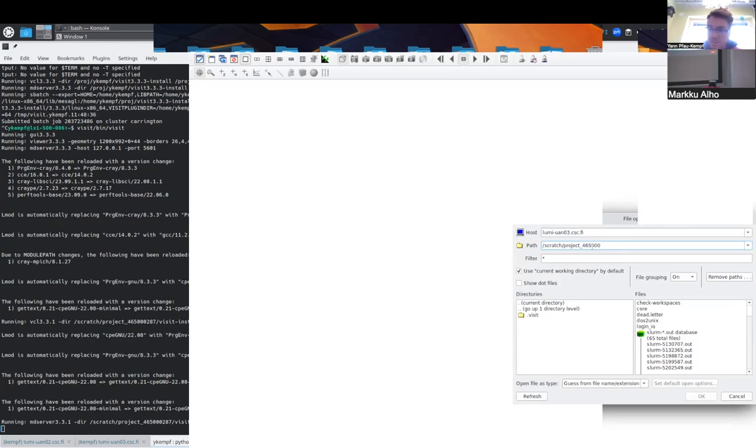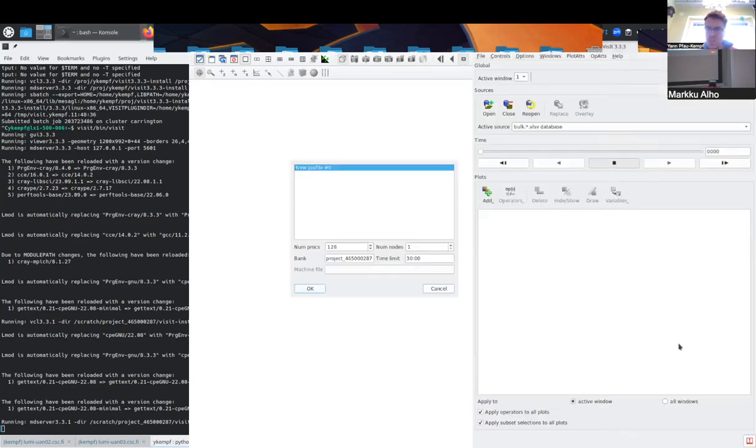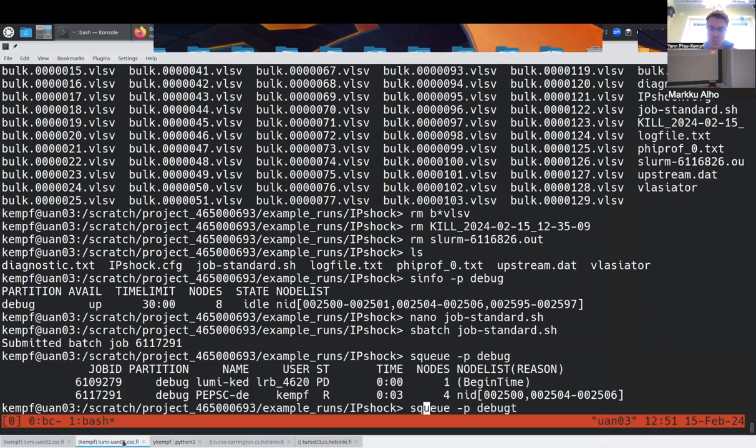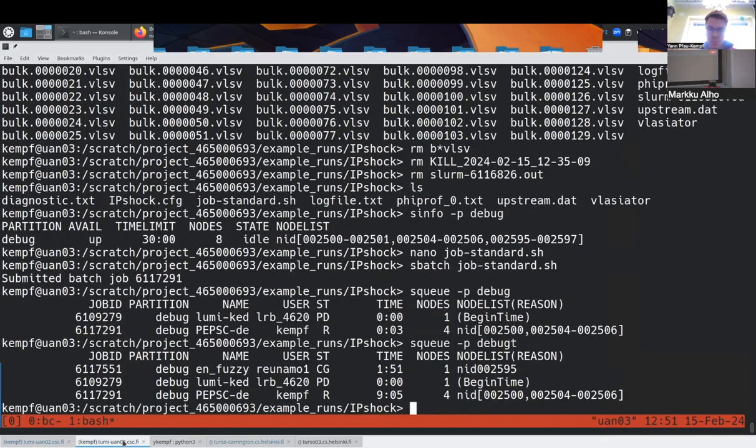We've actually used it in the past before we had fully time varying inflow conditions that could interpolate between these different lines. What we did was simply swap out the SW.dat file for a different one to trigger an instantaneous pressure pulse going into the simulation domain. But yes, there is indeed an extra level: if you're changing the parameters, you need to change two files instead of one.